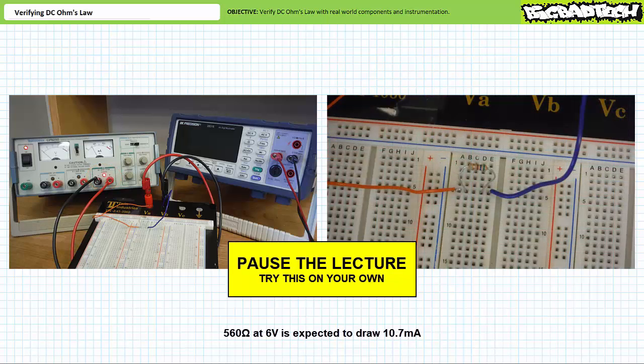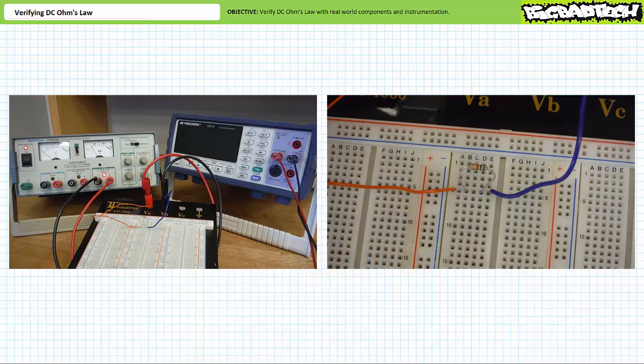By all means, pause the lecture and troubleshoot this circuit. What's wrong? If you're tracking, you should have come to the following conclusion. This is indeed a 6-volt source, and this is in fact a 560 ohm resistor. However, they've built the circuit on the protoboard incorrectly.